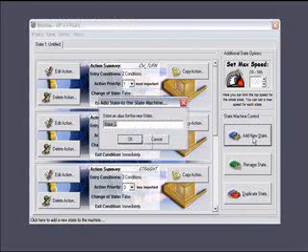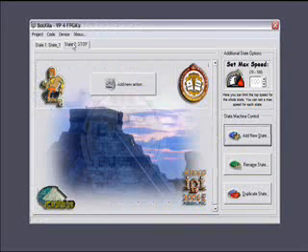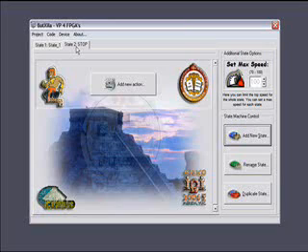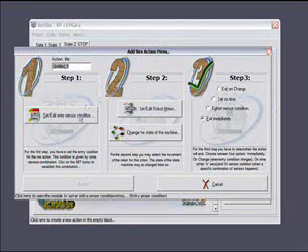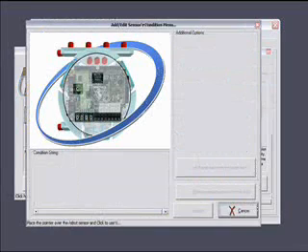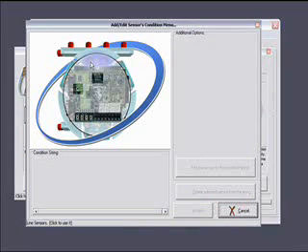We push the button to add a new state, and we will choose a name. As we can observe, a new folder tab has been added to the zone of states that make up our state machine. This state, as it is new, is empty, and it does not contain any action. We will push the button, create a new action, and we will select the entrance condition that suits us. In this unique case, in which we wish for it to stop every time that it enters